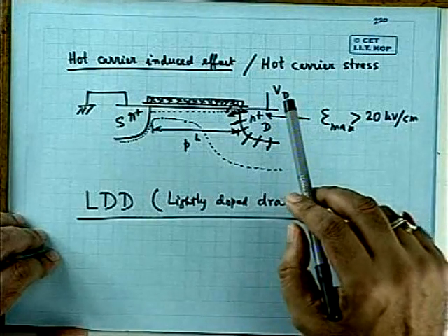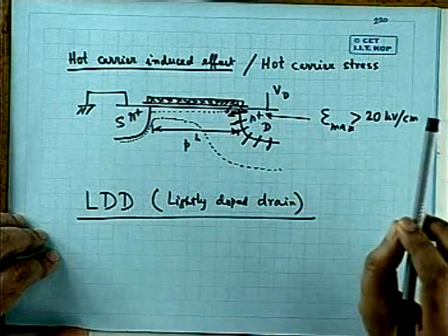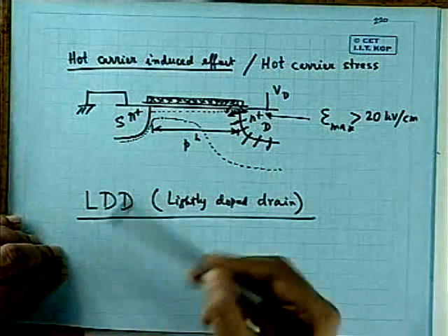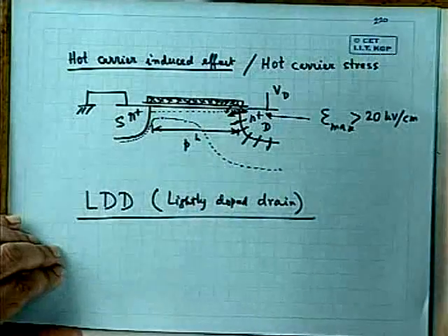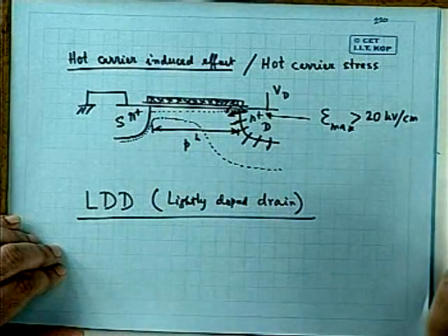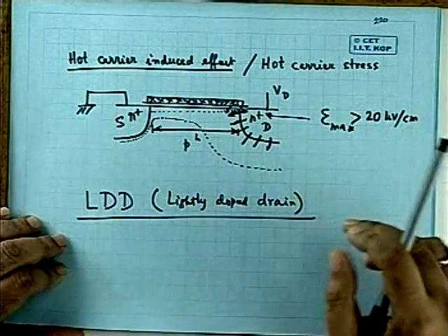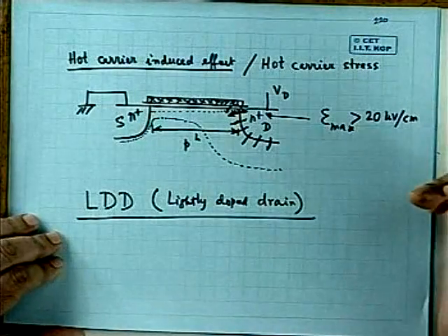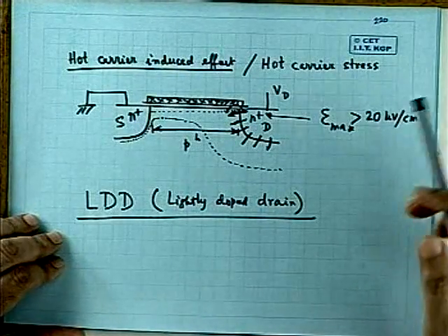This is specific to the ultra small, miniaturized transistors, because any reasonable voltage of the order of a few volts will create a very strong electric field, compelling the carriers to move at a very high velocity. Because of the strong field, hot carriers are generated. And secondly, because of the strong field and ultra thin gate oxide, the tunneling probability is also more. Because of this combined effect, some of the states, bulk traps as well as interface traps in the oxide, get filled with electrons, causing a shift of the threshold voltage, and hence a change in the IV relationship of the MOSFET. Is it a permanent failure or temporary failure? After a long time, the failure may be restored, but gradually the failure takes place, and ultimately there is a permanent failure of the device.